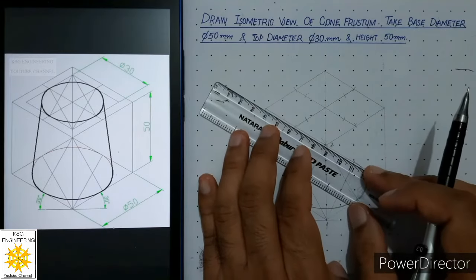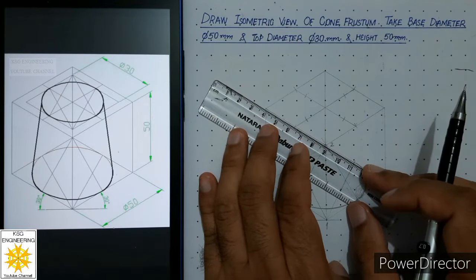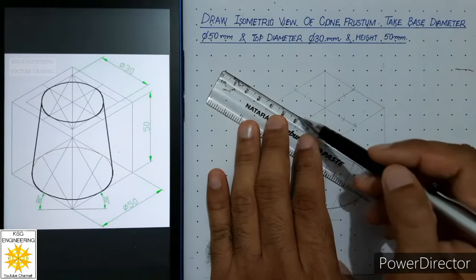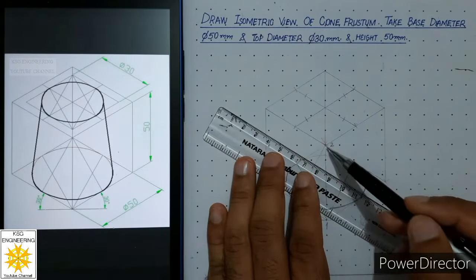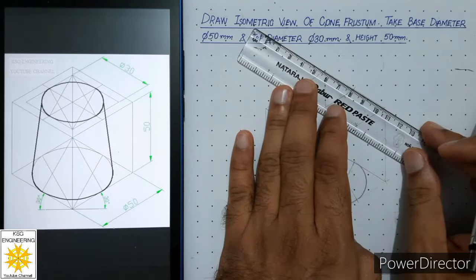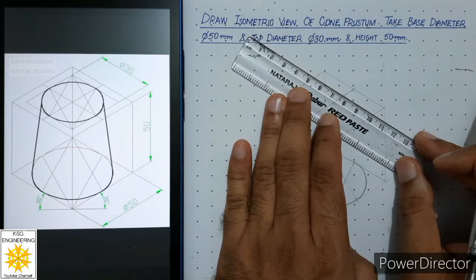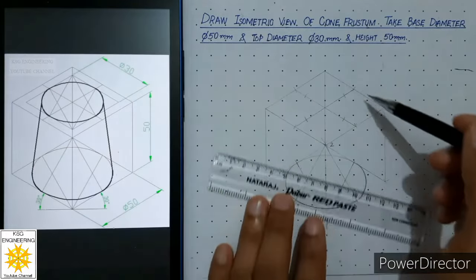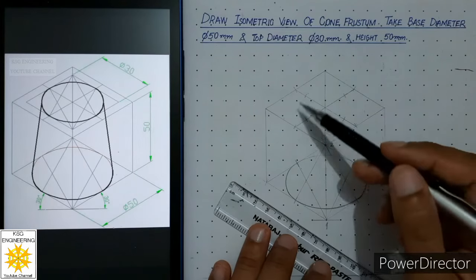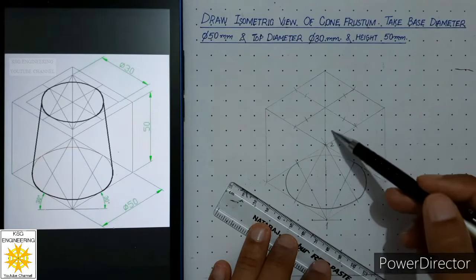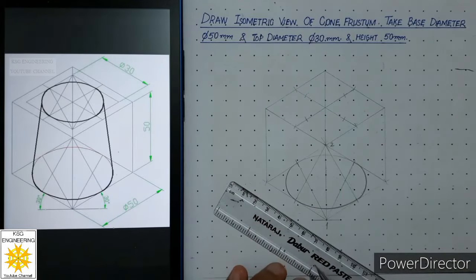Similarly, we will place our roller scale aligned to this edge, and we will carefully roll to this point. We will draw another line which will be parallel to the outer edge. Similarly, we will align our roller scale at this edge and we will roll back carefully to this point marked by us. We will draw another line which will be parallel to outer edge. So by doing this step, we will generate a box of 30 by 30 over here.